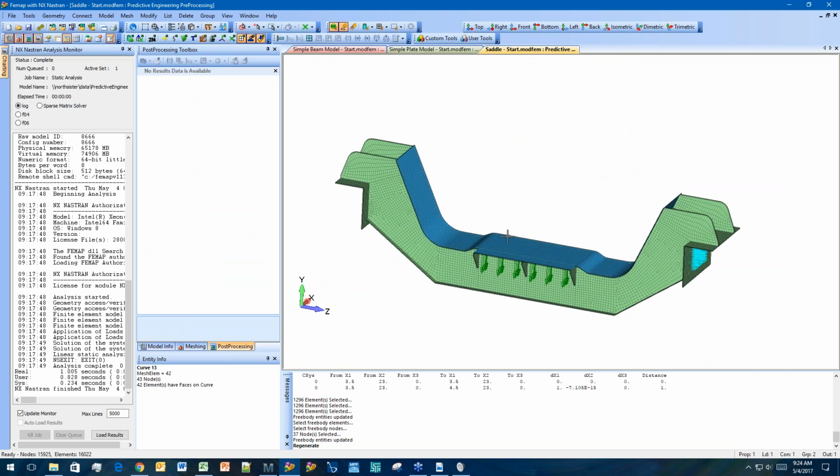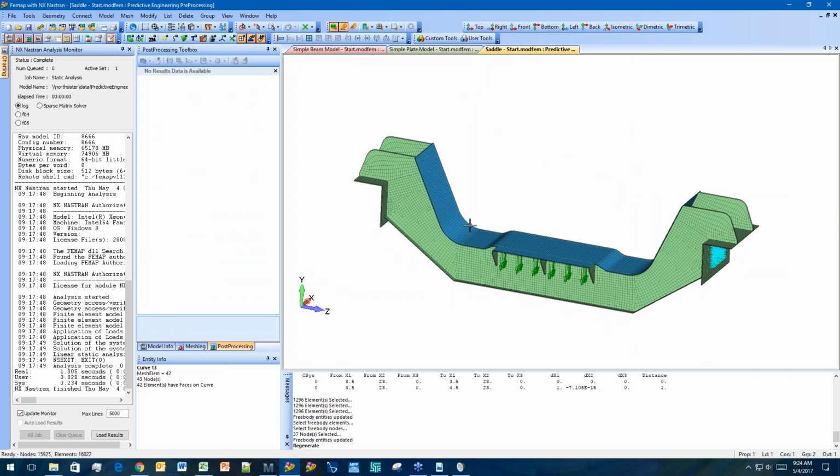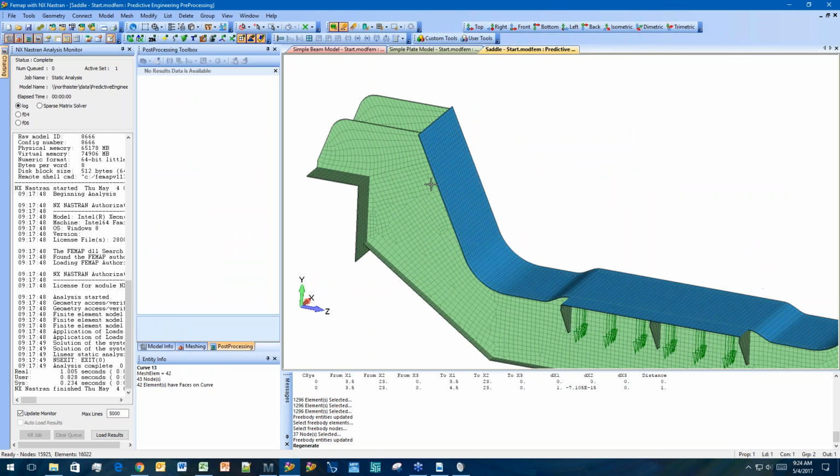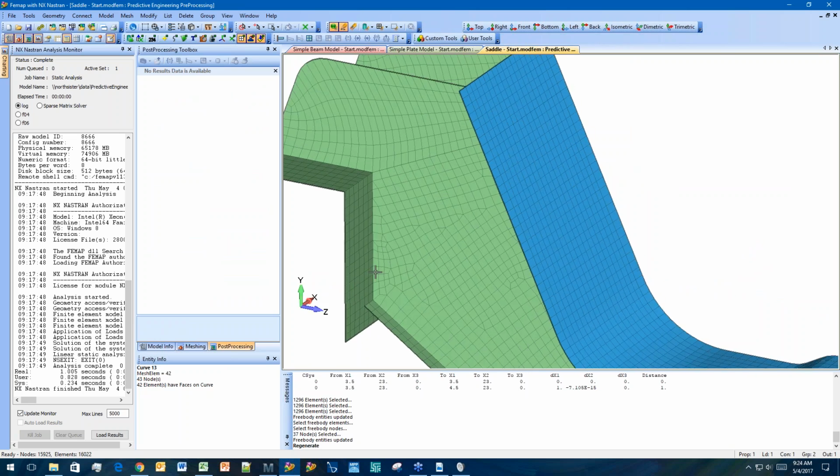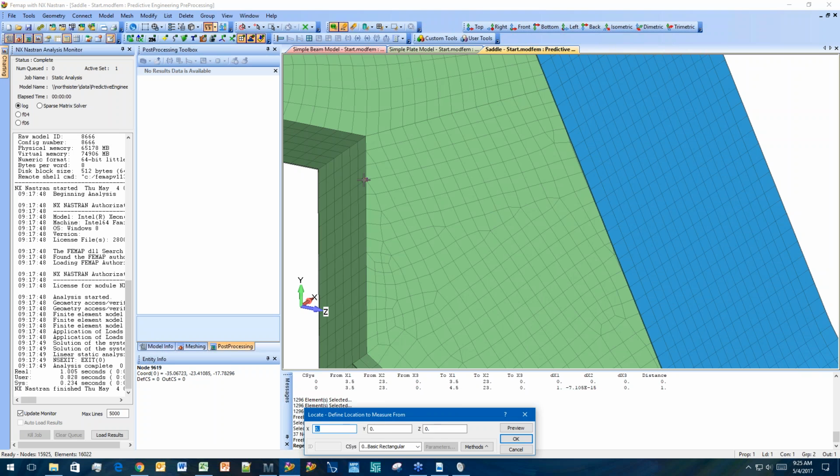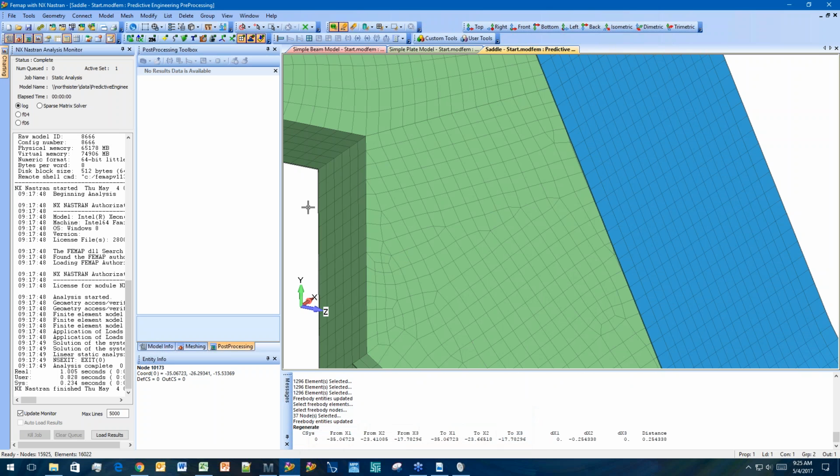And you can play with that in this last model that we were going to include in our workshop files. And one last thing to note on this model is the node spacing along these welds is 1/4 inch. So in this case, when you pull out your forces along those nodes, you just have to keep in mind that you've got 4 nodes per inch. So your nodal forces aren't directly your weld force per inch.